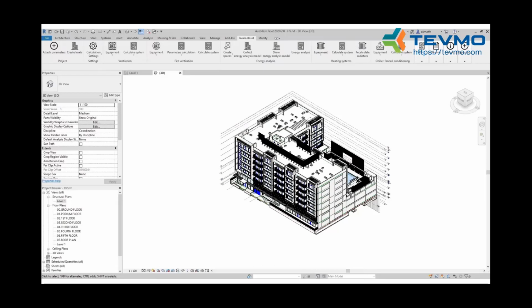In fact, it collects the whole building and builds an energy model of the whole building. In our software, as I just showed you, you select the typical levels, and you do not need to input information on them, and the calculation is much faster. Our calculation and energy analysis is done for the floors that are not typical. So it's also a big benefit. It saves a lot of time.